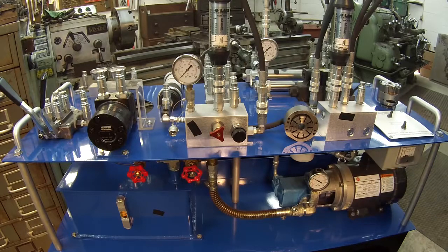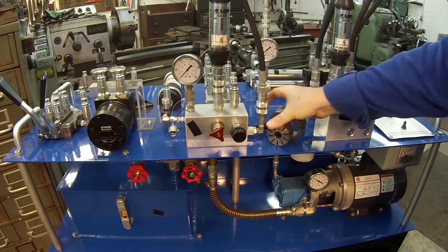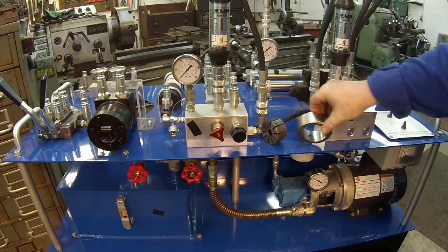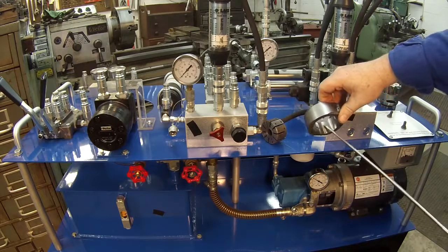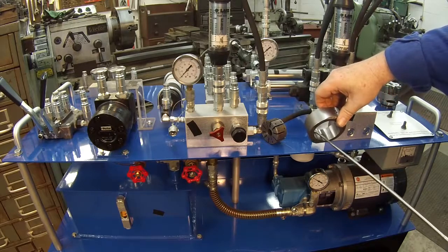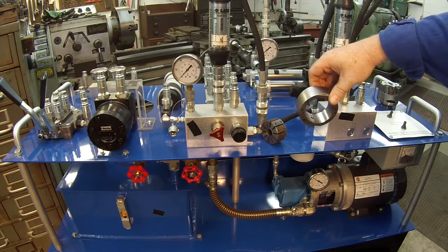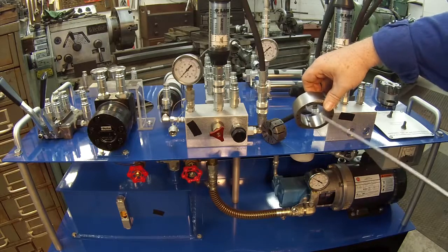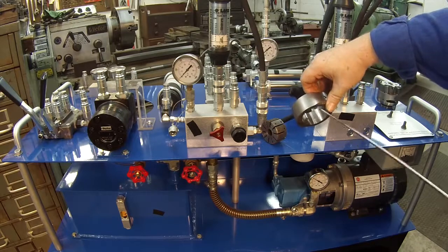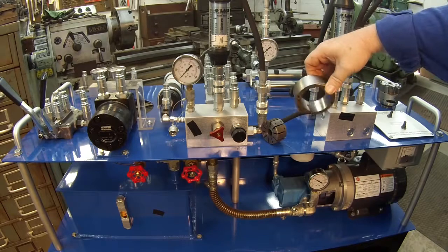Okay? So how that thing fails, your pump, is when you cavitate it, you get these nice little divots right here, these little chatter marks inside your ring. So when you fail a hydraulic pump, take it apart next time and see what the ring looks like on your vane pump right here. Those little chatter marks right there says that I've got some cavitation problems. Okay?